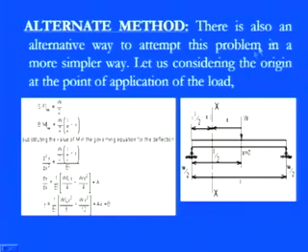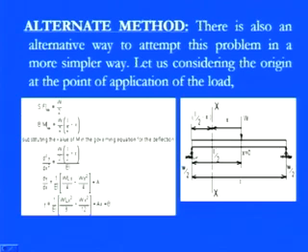With that consideration, we simply cut this beam at the x-axis section, at a distance of x from this load, and since this is L/2, this distance is L/2 minus x. Now we follow a similar pattern: first we find the shear force, which equals W/2. As for sign conventions, I focused on the left-hand portion on this screen, where the reaction forces go upward and the load is downward. With this loading condition, the shear force has a positive sign, so the shear force at the x-axis section is W by 2 due to the reaction.